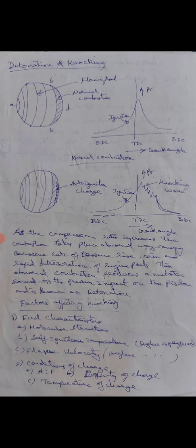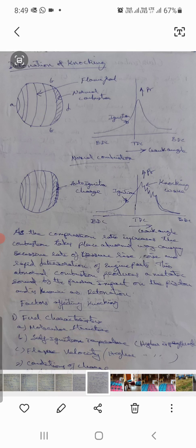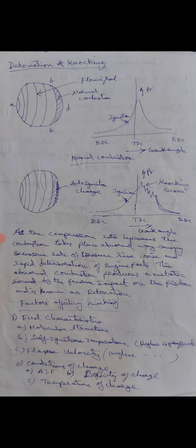Due to this rapid deterioration of the engine parts, because of the abnormal combustion, a metallic sound will be produced. Due to the pressure impact on the surfaces of the piston and cylinder, this is known as a detonation or the knocking effect.